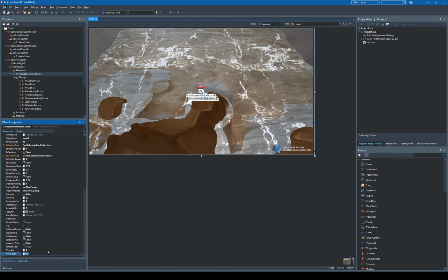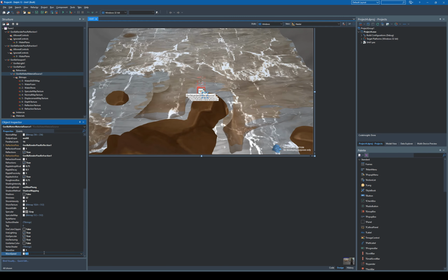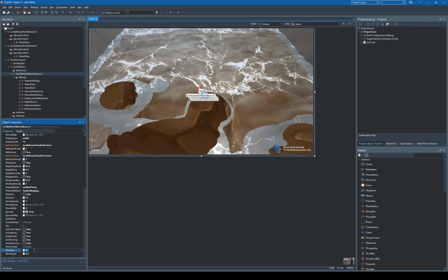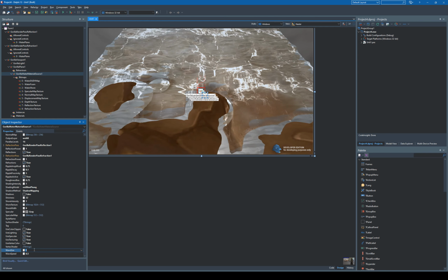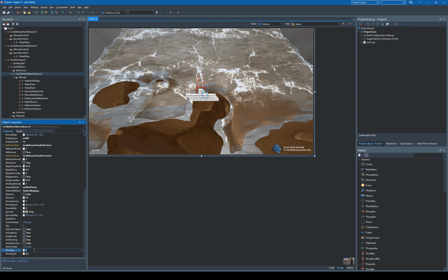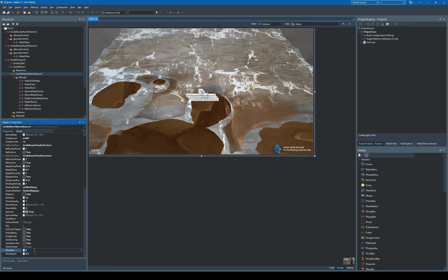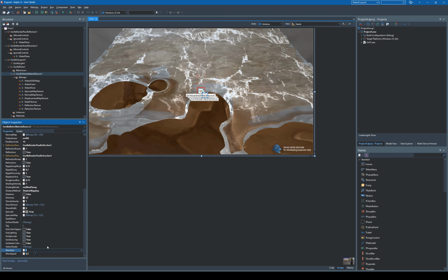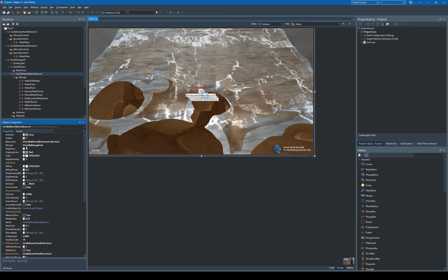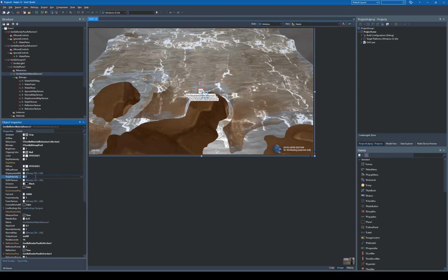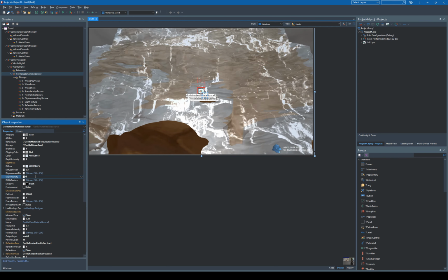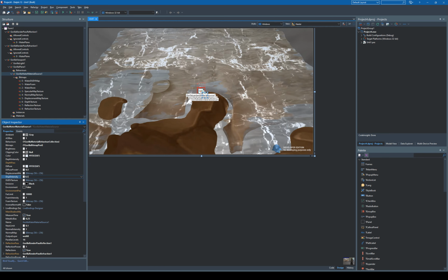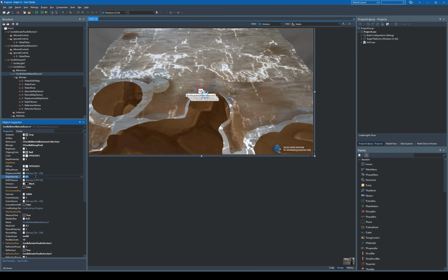The second property is wave size, defining the amplitude of waves, which means how high or low waves are simulated, but this value does not manipulate mesh vertices, only the optical waves. The already mentioned displacement intensity controls how intense vertex shader waves are. Increasing this value makes our waves larger, and lowering the value reduces the effect. Let's set it to 0.5.